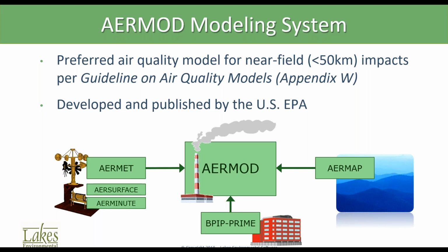We have the BPIP prime program, into which we put in building geometry so that we can estimate building downwash impacts on releases from point sources. And then we have the AERMAP preprocessor, which reads in digital terrain files and puts elevations into receptors and sources and other model objects that exist within our AERMOD project. So all of these components are coded and developed by the US EPA. And whenever there are updates to those, we have to then update our air quality projects accordingly.